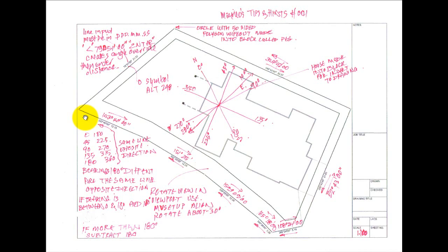So what it does, it sits over the top of a line. So if you do draw a line and it shows up through the wipeout, you can just click on the line and right click on the line, and then using the draw order command send the line to the back so that the wipeout comes to the front, and you just get a nice clear little circle like that.